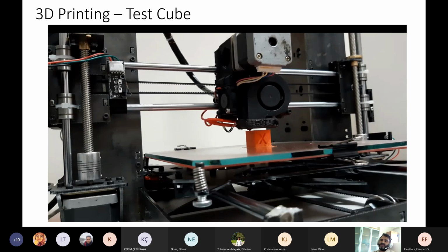The plate you are trying to print on must be compatible with the head. This tray is also heated, so there is a heater under the bed that maintains an even temperature on the bed surface. This is important so that the plastic does not undergo a significant thermal change when it comes out of the extrusion head and adheres to the table. It must be kept at a relatively constant temperature or it will shrink and separate from the table.